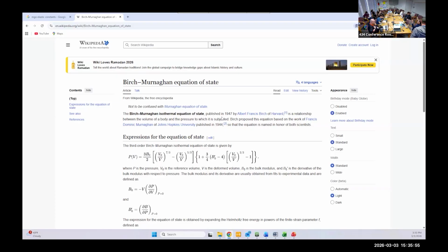People compile all this ceramic data, and most of the data would say that alpha K, the thermal expansion times the bulk modulus, pretty much remains constant, because the opposite effects cancel out most of the errors. So for the first approximation, you basically just use alpha K at ambient pressure and temperature to estimate the thermal pressure, and you do the correction. But it's important to keep in mind this is not precise enough.